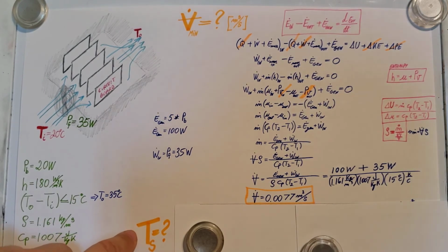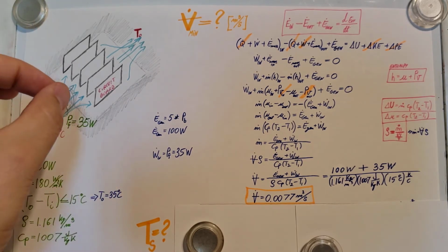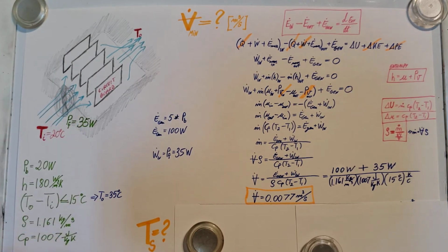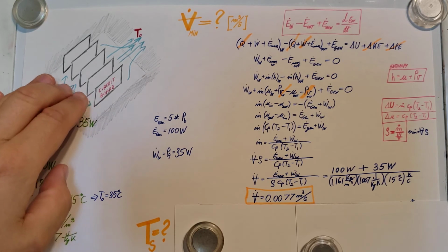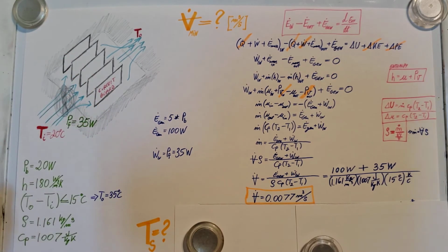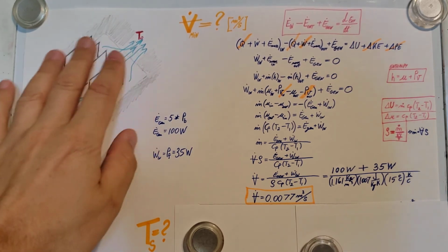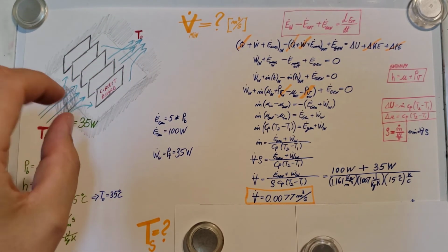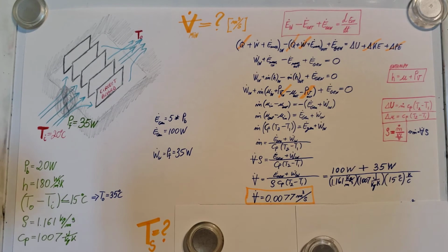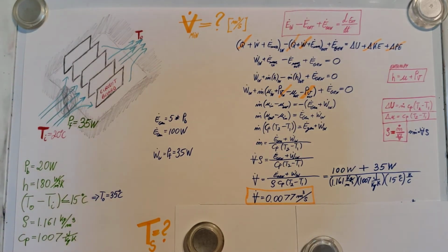They tell us that this component has a very high temperature sensitivity. So that means we want to make sure that in no chance it gets overheated. We want to place it somewhere in this box in a location where it gets the best chance of being cooled. They also tell us that the heat flux on the surface of it is 1 watt per centimeter squared.